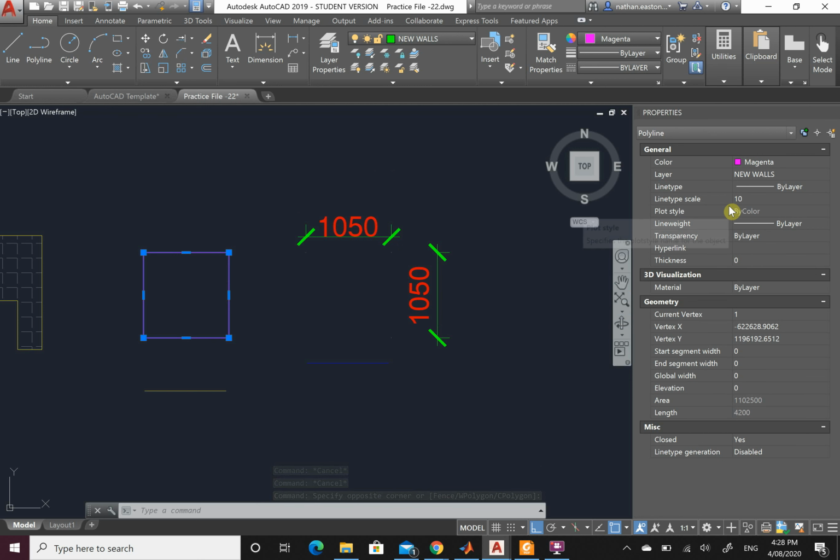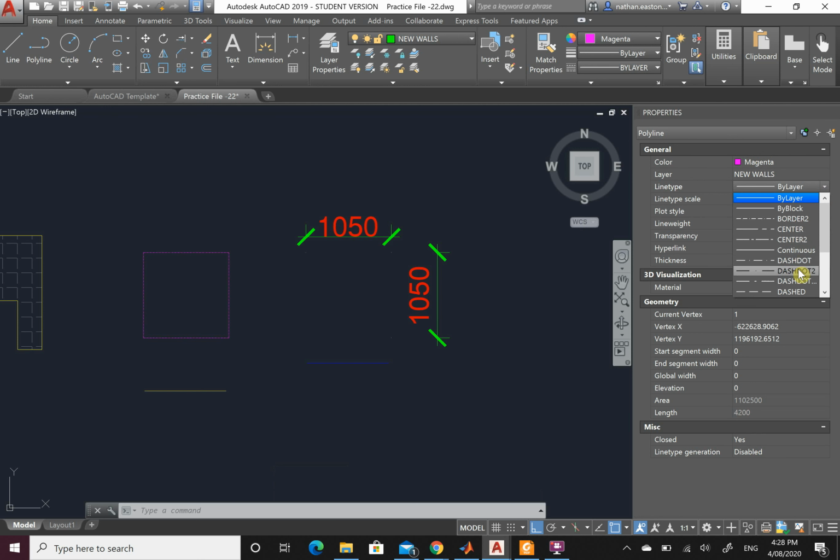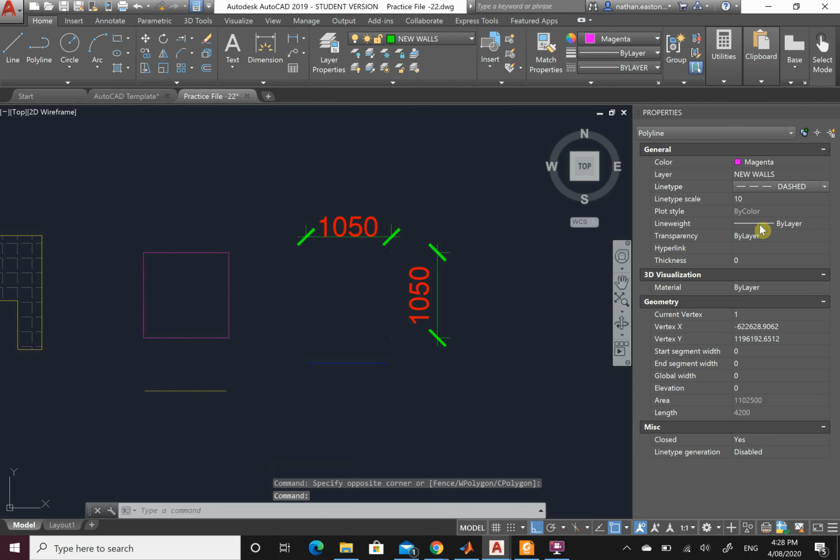Something we do a lot of are hidden lines. So hidden lines are for beams or supports or anything that you can't see from the outside. So our footings will have any supporting beams for our lintels, for our rafters, or for anything like that. We come through our line type and we change it to dashed, or dash dot. Alright, change the scale here, 500. What it's doing is just making this like we did before with the hatch, same thing, 1500. Okay, that's a bit too big, 500 looks a bit better. Okay, or even 1,000.